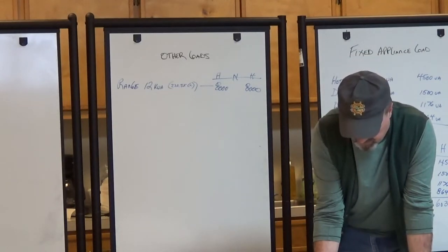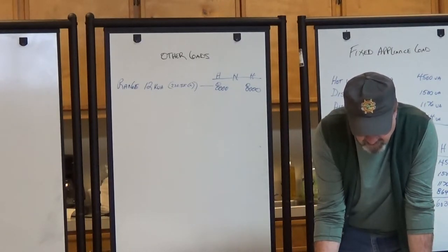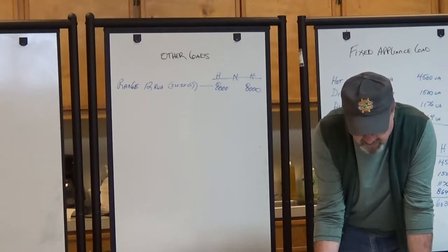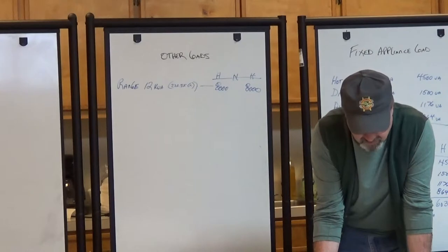Yes. Page 70-67. It says a service or feeder supplying the following load shall be permitted to have an additional demand factor of 70% applied to the amount in 220.61(B)(1) or portion of the amount in 220.61(B)(2) determined by the basic calculation.